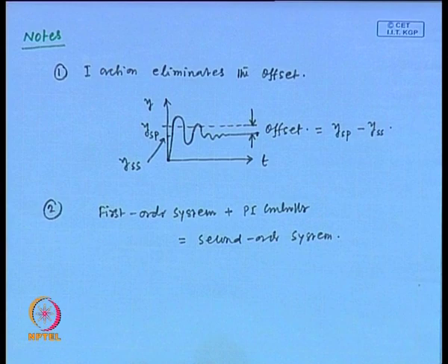Now, in a plot we have compared the dynamics of first order, second order and fourth order systems, and we have observed that increasing the number of capacities in series increases the sluggishness. So, by that line we can say that by the inclusion of integral action, the order is increased by 1. It means the overall response becomes more sluggish. Fine. So, this is the second conclusion.